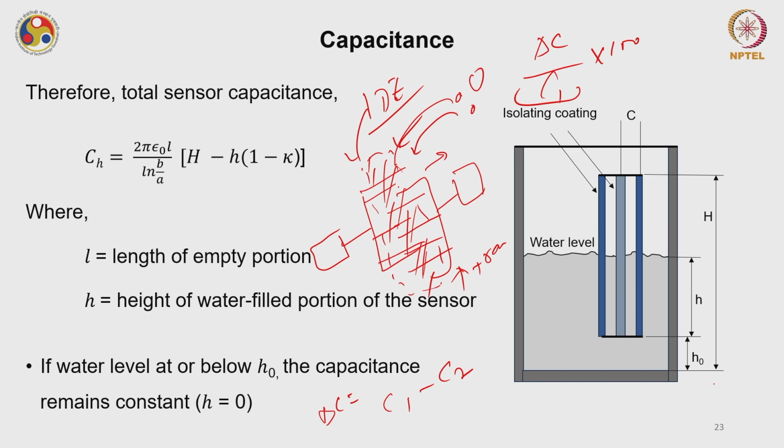There can be other conditions also, like I have given examples of a proximity sensor, a pressure sensor, relative humidity. Now in this example only, just replace these gas molecules with water molecules. What will happen? Again the same thing: the water molecules interact with the sensing layer, depending on what material it possesses. Either you can have electron conductivity or proton conductivity.